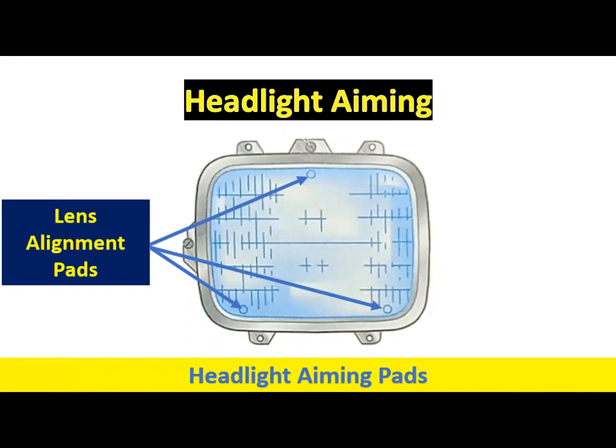So the typical replacement procedure for a halogen bulb in a composite headlight is: be sure the headlight is switched off, place fender covers over the vehicle body in the work area, remove the cap over the rear of the bulb, remove the wiring connector from the bulb and remove the retaining spring, remove the bulb from the composite headlight.